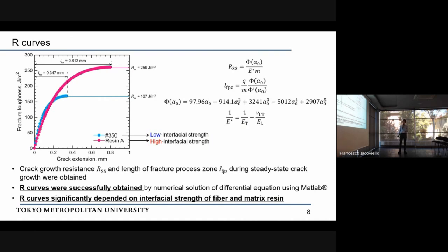Our R curves were successfully obtained by numerical solution of differential equations using MATLAB. And I think that this is the first attempt to obtain R curves for transverse cracking experimentally. And our R curves significantly depended on the interfacial strength of fiber and matrix resin.